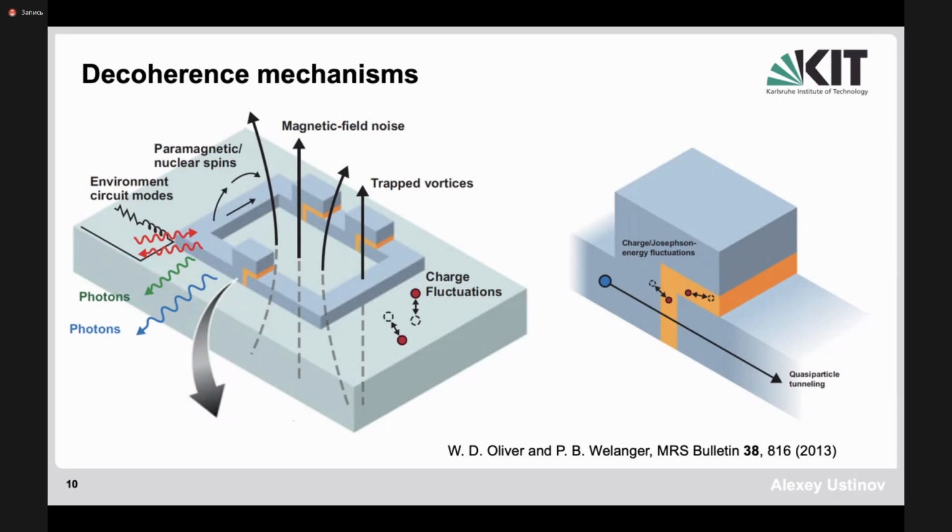So, for example, in devices which are most sensitive to measure magnetic fields and magnetic field noise, in devices like SQUIDs, the noise is always limited by roughly 10 to minus 5, 10 to minus 6 of the flux quantum. Interestingly, it's independent of the area of the SQUID, it's independent of the material. It's a very fundamental limitation of the noise in SQUIDs. And this has really been the subject of many investigations in the past. The physics of noise in SQUIDs is largely similar to the magnetic noise in superconducting qubits, and is still the subject of intense investigations.